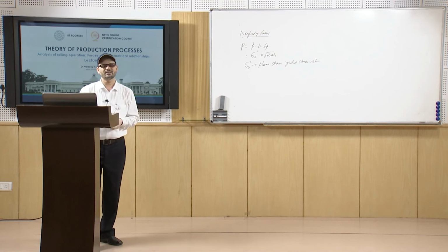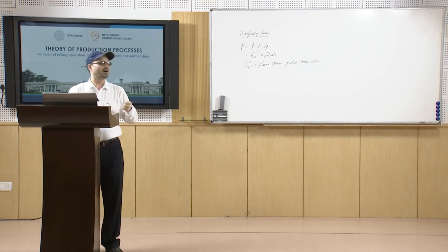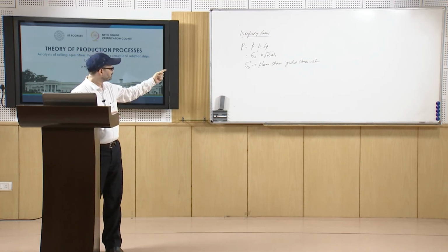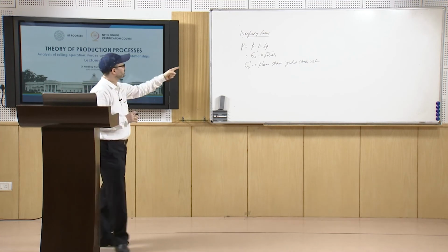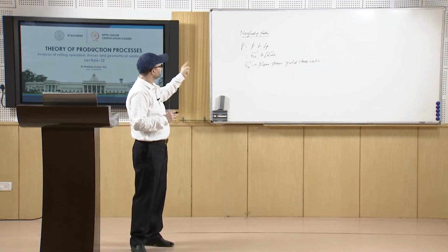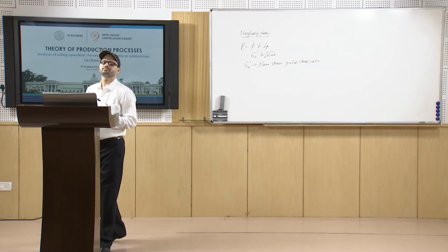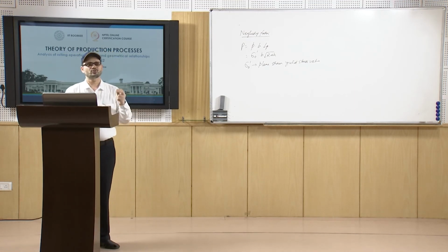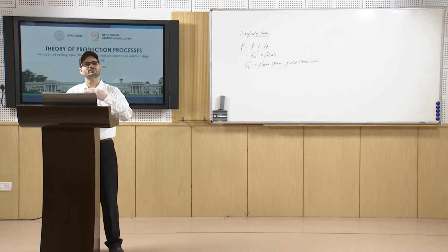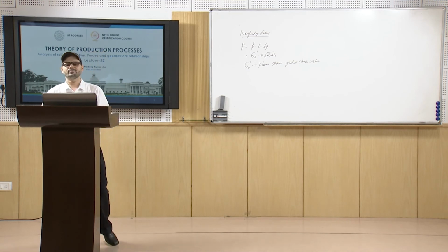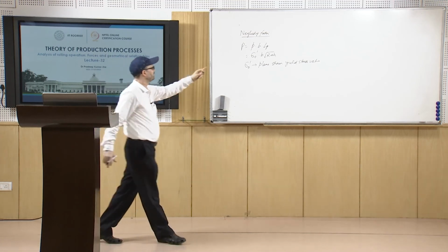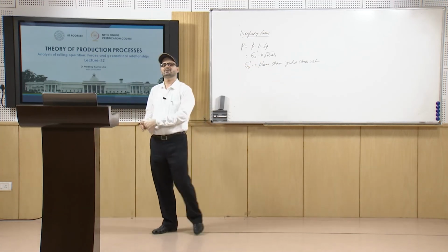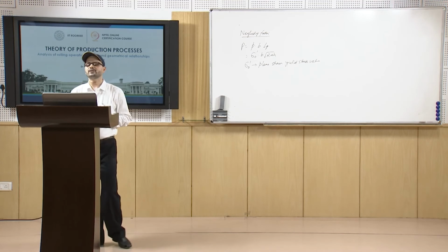Since we have fixed that, this sigma naught prime is the plane strain yield stress value, and you can find the roll load as P equal to sigma naught prime times B times LP. We have already derived the relationship for LP.